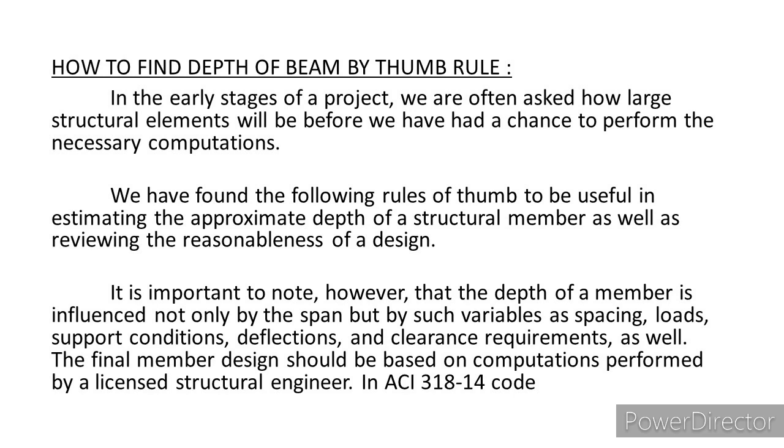It is important to note, however, that the depth of the member is influenced not only by the span but by such variables as spacing, loads, supporting condition, deflection, and clearance requirements as well. The final member design should be based on computations performed by a licensed structural engineer in ACI 318-14 code.